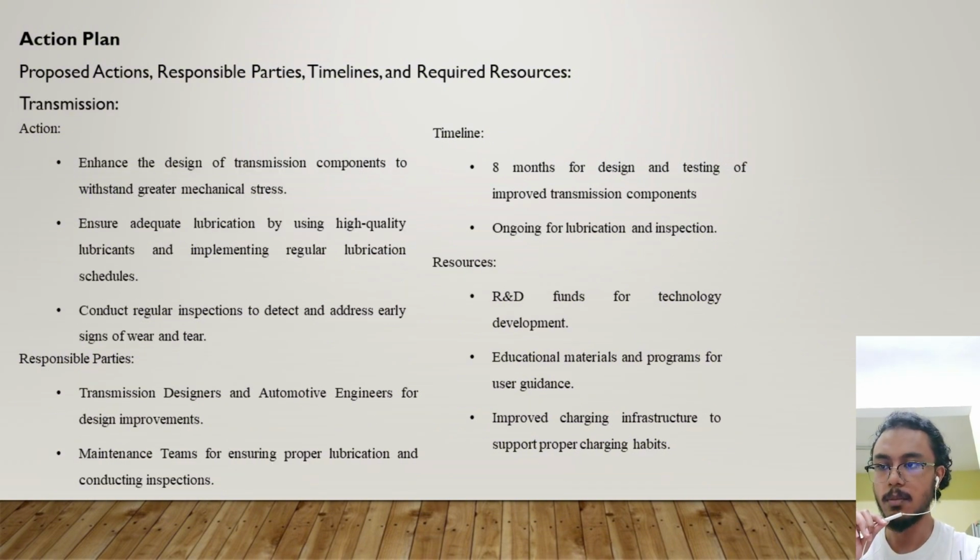Next will be the action plan for the transmission, which is to enhance the design of transmission components to withstand greater mechanical stress, ensure adequate lubrication by using high quality lubricants and implementing a regular lubrication schedule, and conduct regular inspection to detect and address early signs of wear and tear.